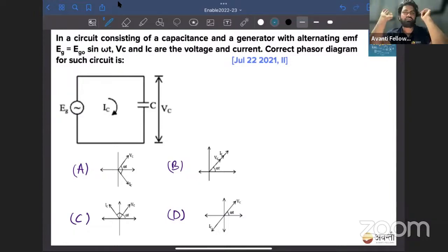As the current, so the voltage, only the values differ. If I put a capacitor in an AC circuit, the current is leading the voltage. For zero voltage, you are getting some current. But for an inductor, the current is lagging the voltage. So for the maximum value of voltage, you are getting zero current in the case of an inductor.